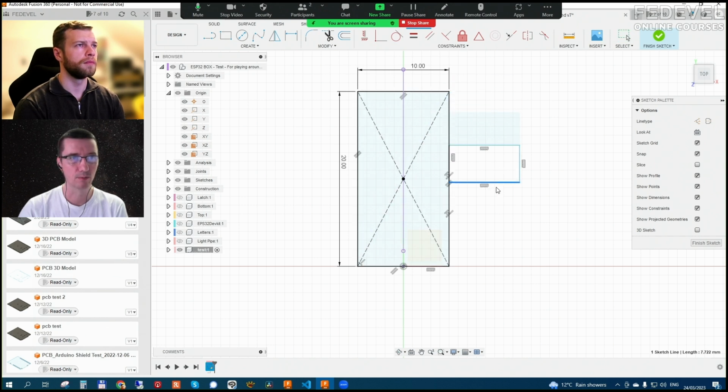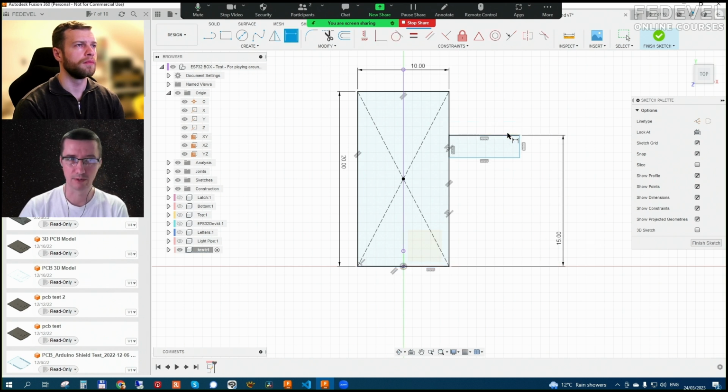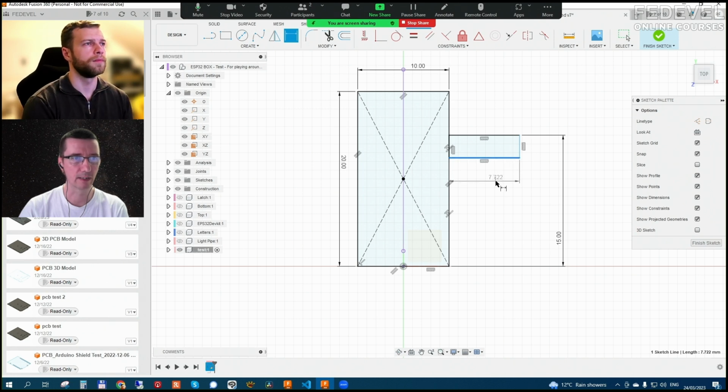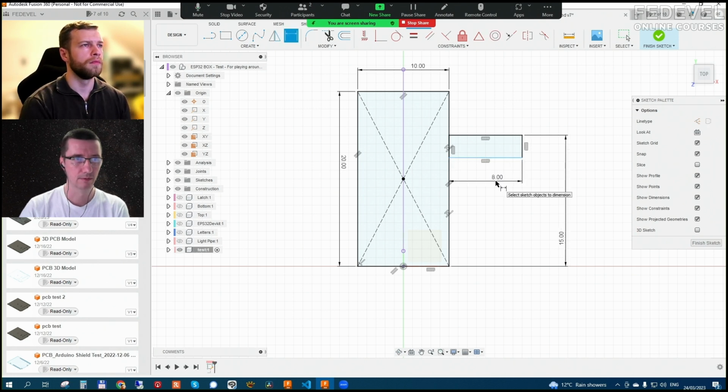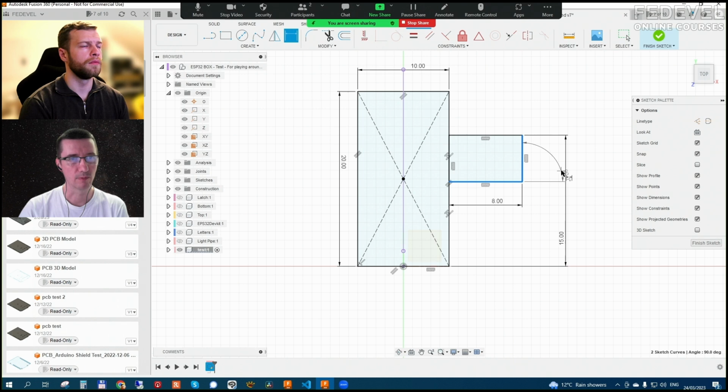So you can always move it and you can see what is not specified. So I know I need to specify, for example, the dimension of this. So you can take it from here to here, and let's say 15. Now this is also black, see? If you specify also the length of this, this is also black, and again, you can see what is still not specified. So we need to specify, for example, the width of this. And then it will be fully, oops. See, now it's all black.